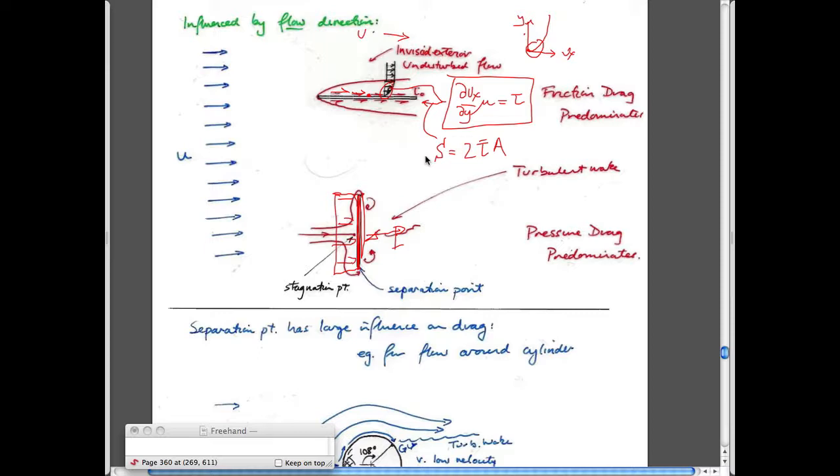So all by way of saying that there are 2 sources of this force that's applied to us. The pressure hitting my chest due to killing the velocity, stagnation, and also the effect of shear. Obviously, in both of these examples, there'd be an effect of shear around here, a small amount, but the relative magnitude of this compared to the pressure is probably going to be small. And likewise, you're killing the velocity here, and there'd be a stagnation point here, so there'd be a pressure here, and a very small area, so there'd also be a pressure force as well. But in each of these cases, this would be mainly shear, this would be mainly due to stagnation.